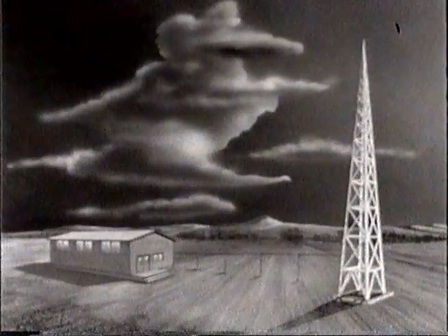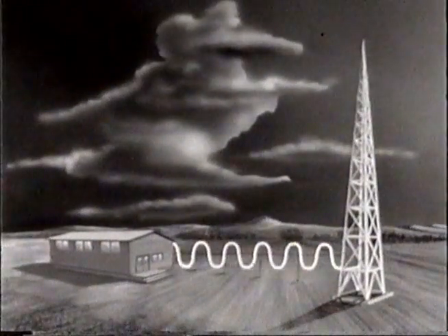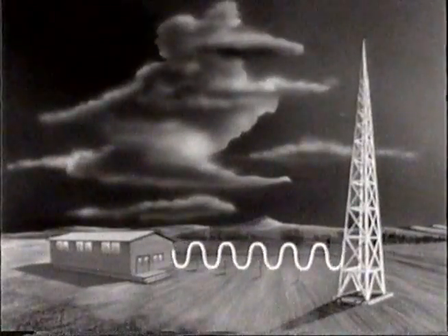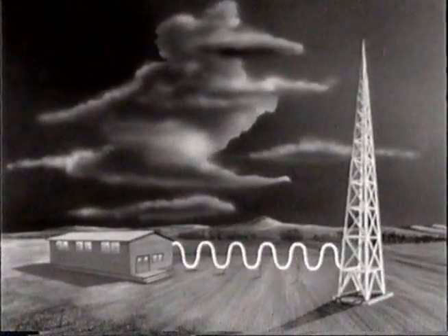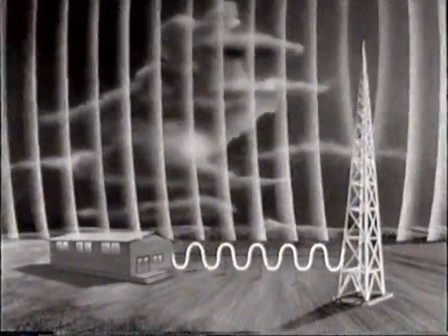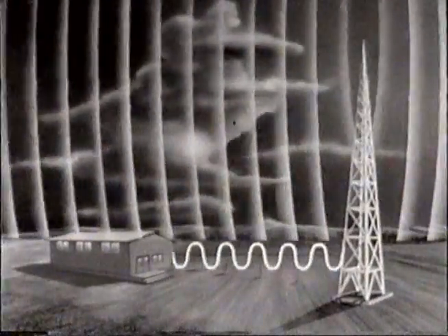Could we see electrical impulses and radio waves, we would see moving over the feed line from the transmitter to the antenna, traveling waves carrying the energy which the antenna radiates. At the antenna, we would see electromagnetic waves being generated and speeding out in all directions. These waves move through space at the speed of light. The frequency of the traveling waves on the transmission line and the radiated waves sent out into space is the same.